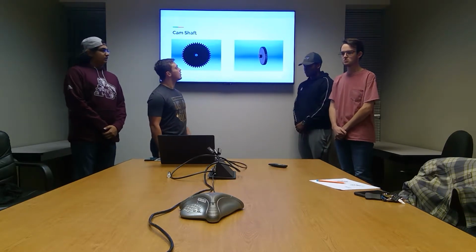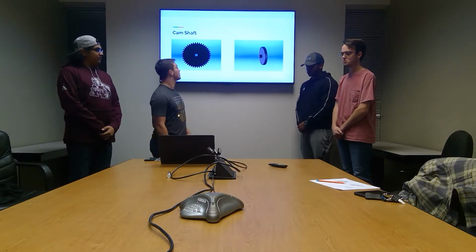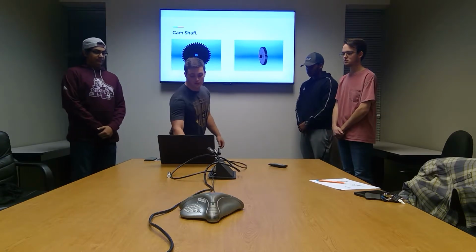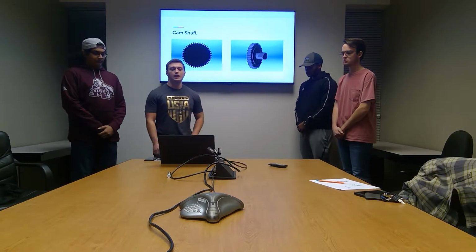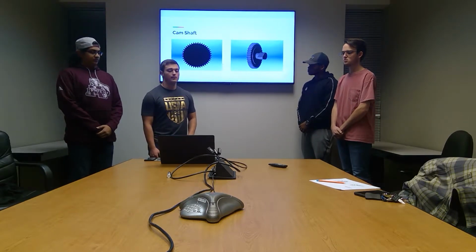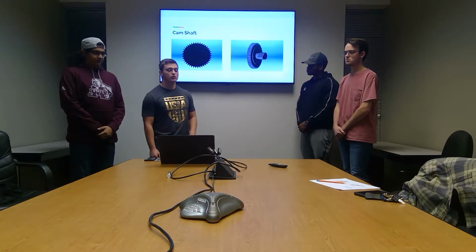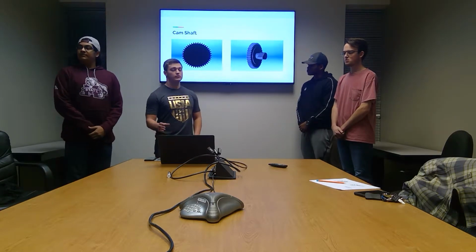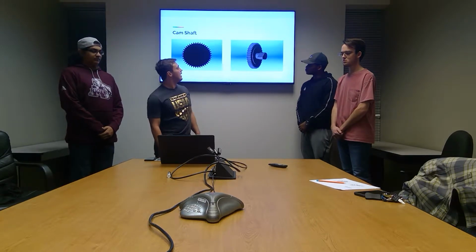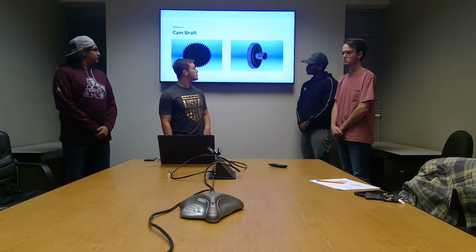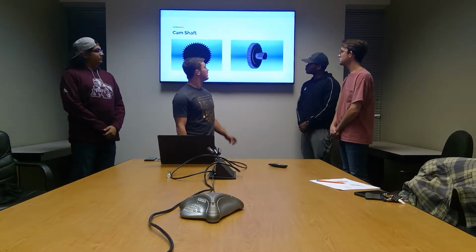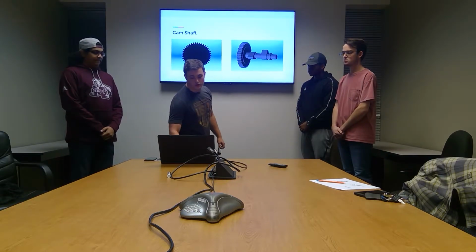The extrude that is closest to the gear is actually extruded through in order to fill the hole that is in the gear, and the other two extrudes are just put on top of it. So then I moved on to making the lobes of the camshaft. The origin of the lobe is the same as the central origin of the part. It's just a semicircle that's tangent to both of these straight lines, and as you'll see later, the tops of it are filleted. It's also got a small thickness right there on the other side of the gear and another cylinder portion that leads to the first lobe.